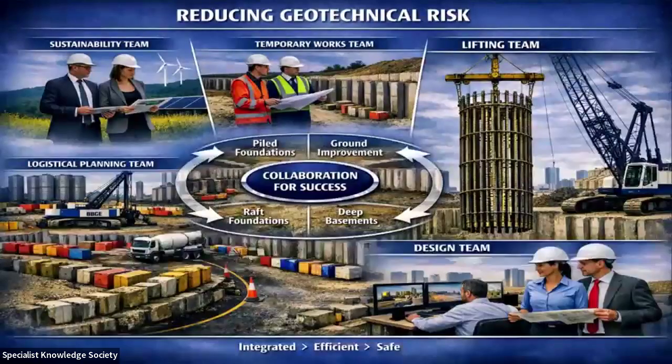Yeah. So again, it's ground condition dependent and length of temporary casing dependent. There is a limit to the amount of casing that you can physically put in and then sensibly extract, if that makes sense. So you put a bit of casing, you leave it in the ground. The ground obviously, it doesn't stick.